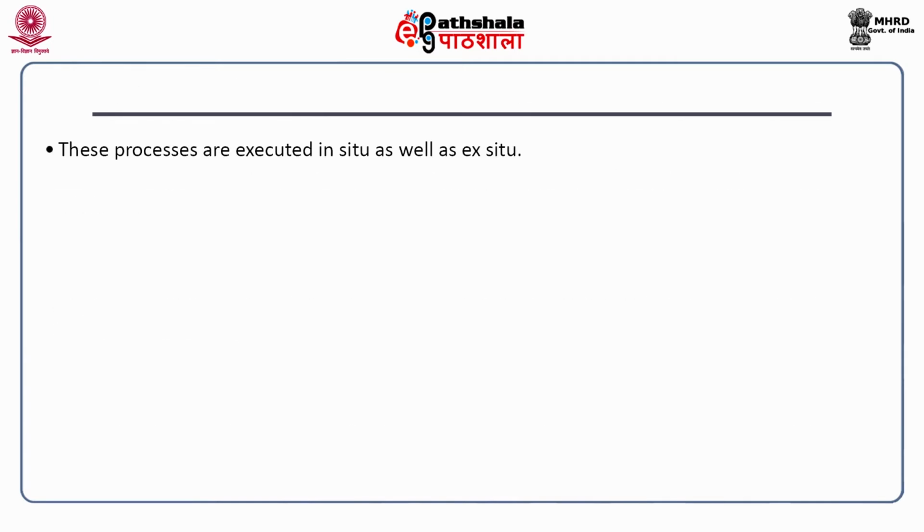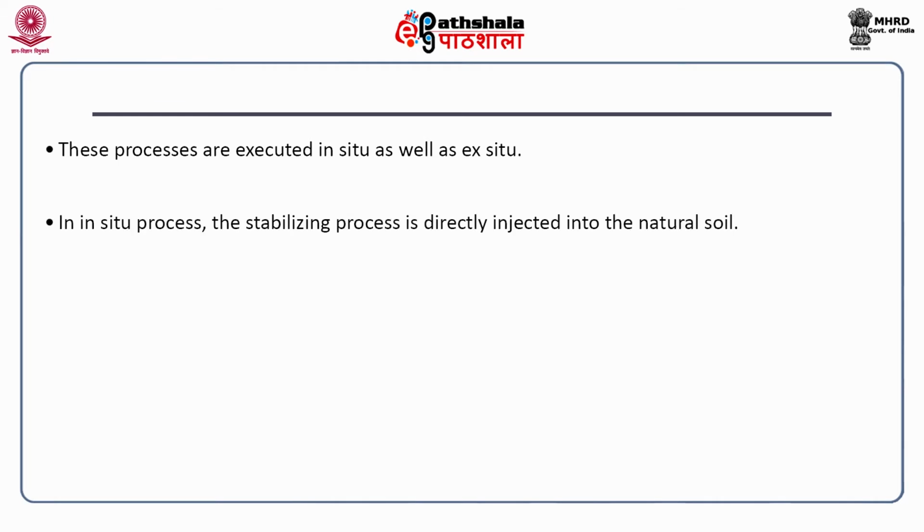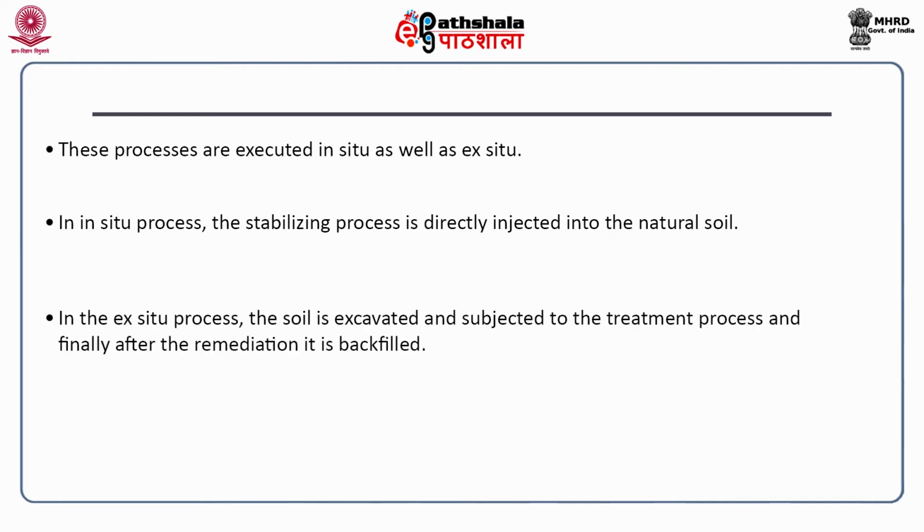These processes are executed in situ as well as ex situ. In the in situ process, the stabilizing agent is directly injected into natural soil. In the ex situ process, the soil is excavated and subjected to treatment, and finally after the remediation it is backfilled.